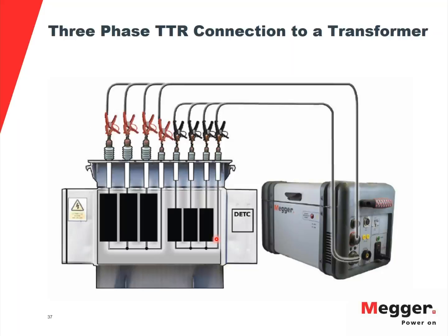If you want to be more proactive, you can connect the primary and delta tertiary in series and do dual injection to speed up the process of core saturation. But those are the things that I would keep an eye on. Make sure that you give enough time for delta winding saturation, because delta windings on the secondary side are kind of tricky. So yeah. Thank you, Dinesh.